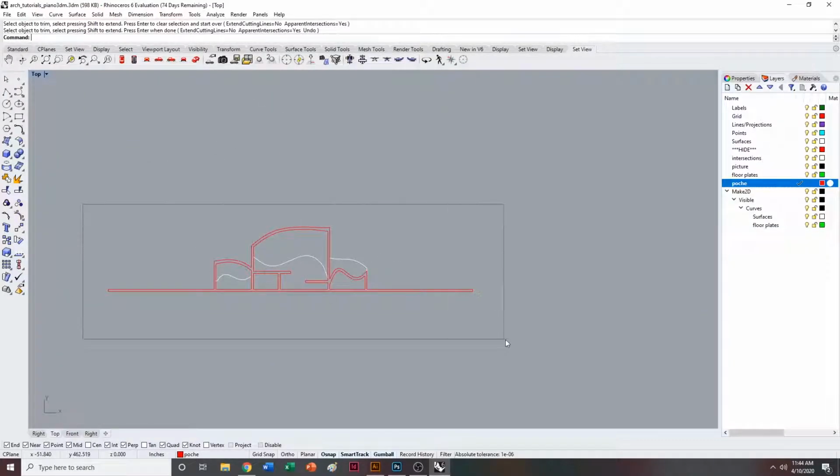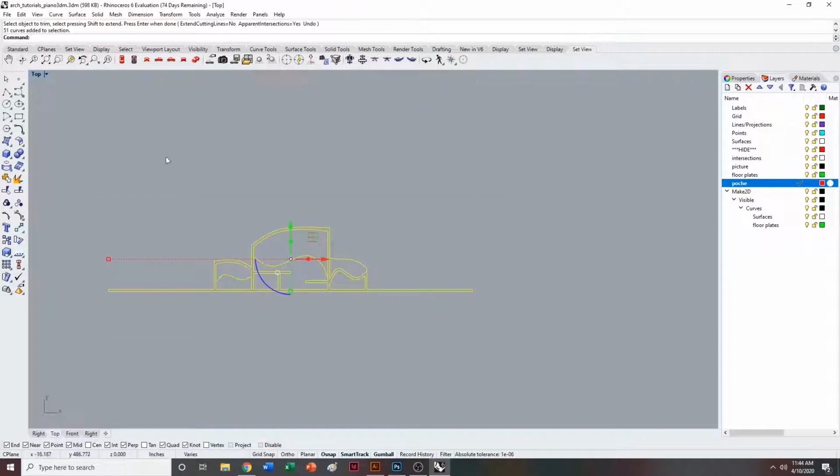So now we should be able to bring this into Illustrator. I'm going to go ahead and type distance and see just how big this thing is. It looks like it's 172 inches. So if we assume that we're going to put this on like a 2-foot sheet of paper, we're going to go ahead and make the scale, I don't know, maybe 100 or 10 inches equals 1 inch, and that should give us about 17.25 inches in Illustrator. We just want to get it to like a rough size so that we can start to scale it once we get into Illustrator. None of these drawings really have a scale that we're requiring you to have.